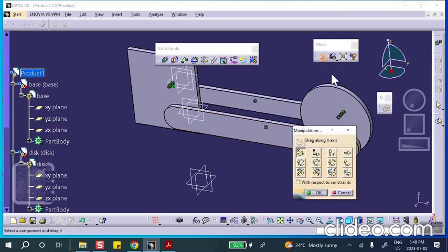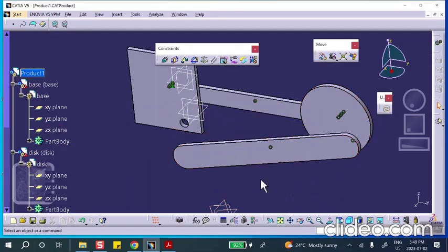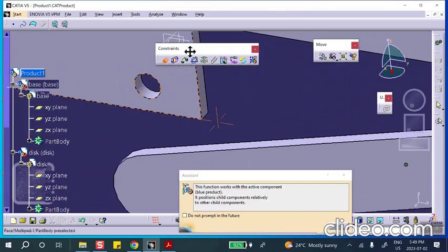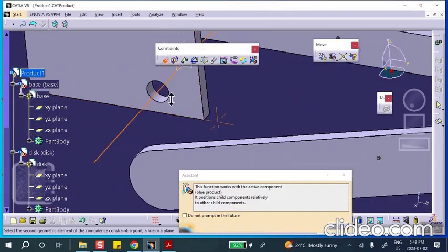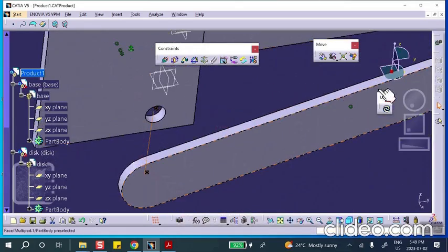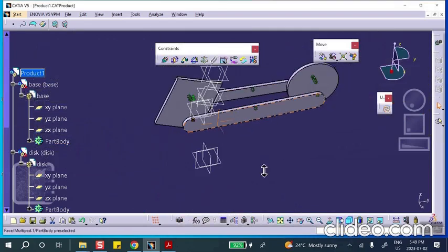let me move this thing a little bit so that I can rotate this thing about the, okay. You see, I don't have to make between this and this revolute. The cylindrical will do the job because these two planes will never get off each other. So I really need only one coincidence here. Coincidence with this axis and that axis. And they'll take care of it. It becomes a revolute joint, by the way.